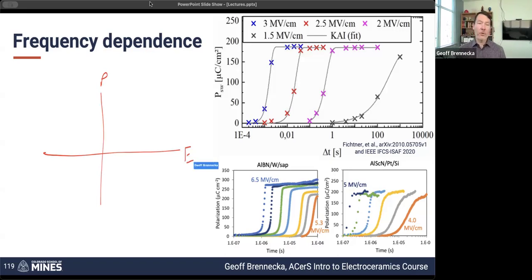We have the same polarization versus field. And now instead of having a perfect material, I'm going to talk about one that has some loss involved. So there are a handful of free carriers that are around that if I apply a DC bias, this looks like it's got a reasonably high conductivity. So it's kind of leaky. So I'm going to again start with a baseline hysteresis loop.